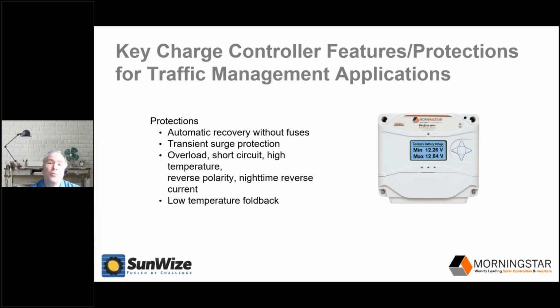In terms of protections, we recommend charge controllers that have automatic recovery without fuses, so you don't have to manually replace a blown fuse to start your system back up when conditions are favorable again. That's very important. Controllers should have transient surge protection to protect against nearby lightning strikes. They should also have overload, short circuit, high temperature, reverse polarity, and nighttime reverse current protection.